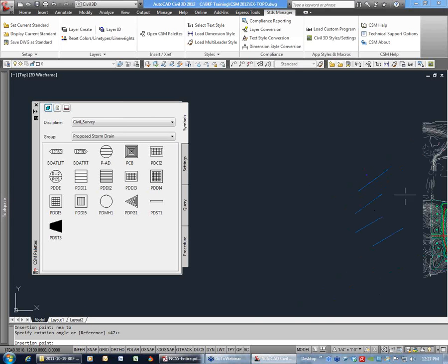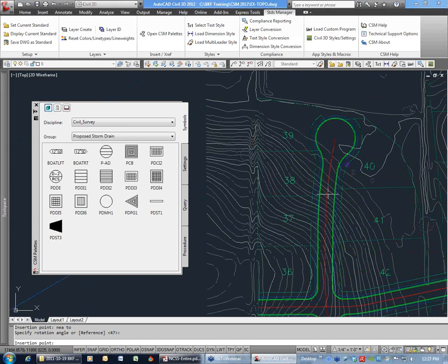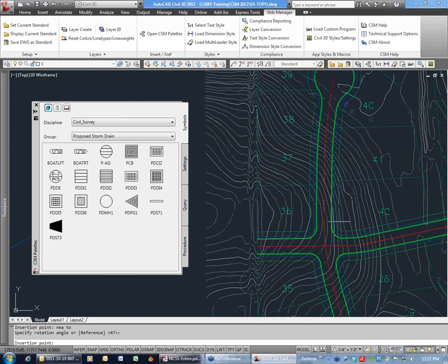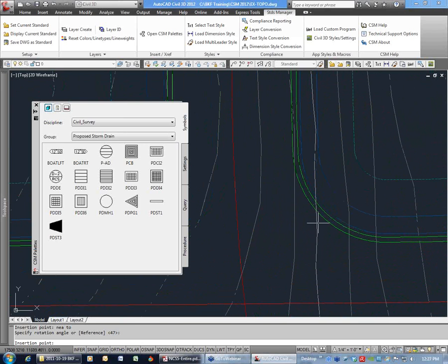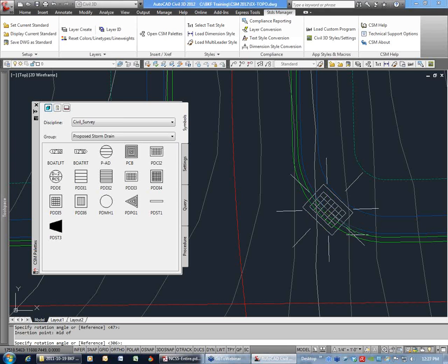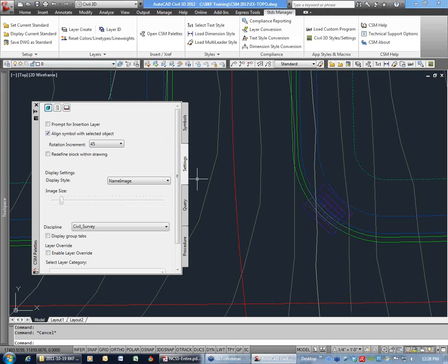So if I snap to anything, this can be anything. This is just lines. If you guys remember, the subdivision in here is actually an X reference. So I can also snap to an X reference as well. So if I do out of a midpoint of a curve here, it'll rotate to that. Okay. So it gives you a little extra functionality for rotating when you're snapping to a symbol. And of course, you got the same thing as before, is it'll scale it as well as put it on the right layer. Okay, so that's a nice little function here for the align symbol.